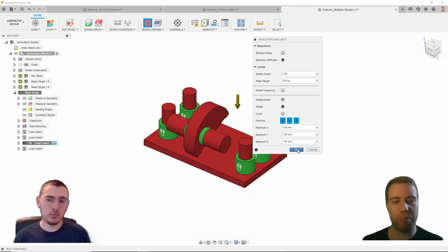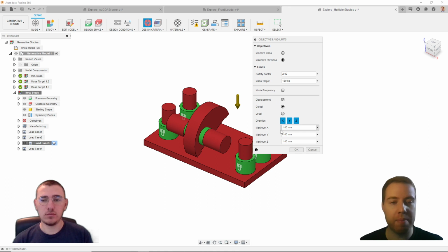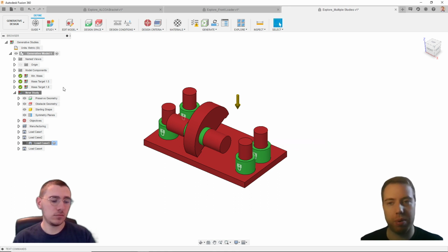We might also come up with a simpler design. So sometimes when you see generative design outcomes, you get these really organic freeform shapes that are theoretically optimum, but sometimes they look like they've almost had too much mass taken out, and that's going to make them harder to manufacture, for example. So again, this is an interesting way we can still come up with optimum designs, but often we're wanting to balance performance against things like cost. So running multiple studies is a great way to explore those different possibilities.